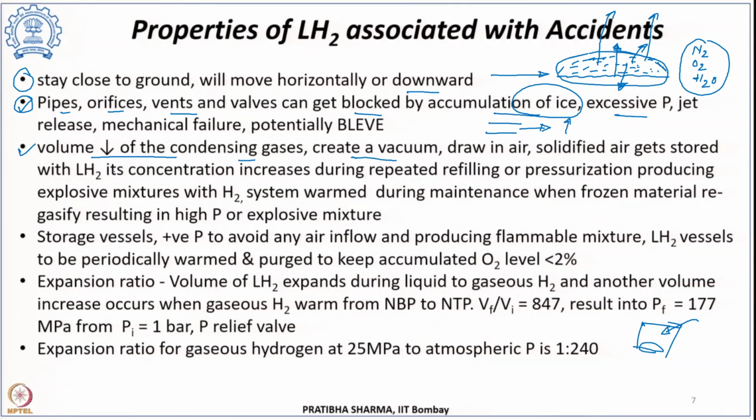The volume will be reduced due to condensation of the gases, and it will create a vacuum, and due to the creation of the vacuum inside the tank, it may draw some air inside the tank.